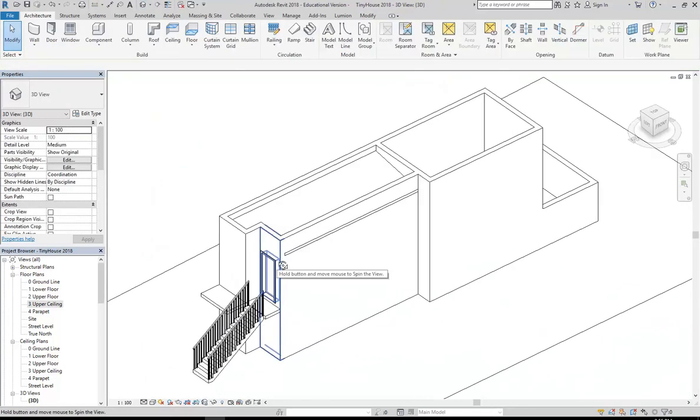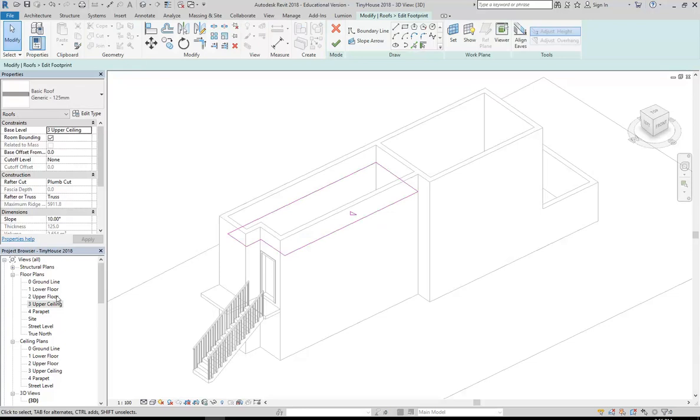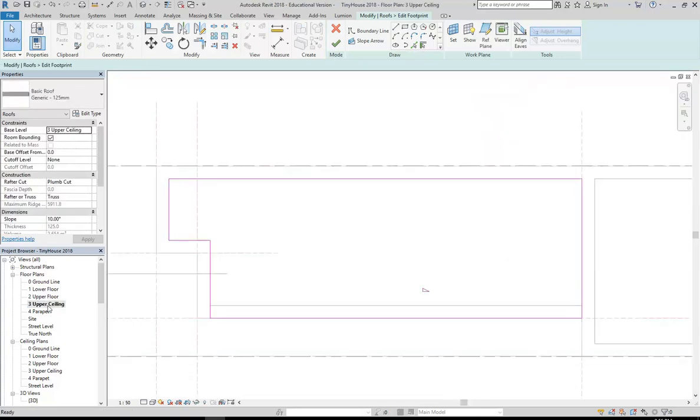Can I ask, I use the same on my outside wall and it has now gone into the inside, so it goes internally instead of externally. Yeah, that's right, because you need to look at the way you make the roof edges. You did exactly what you do, like pick the outside one and then the rest. But did you use pick lines or pick walls?